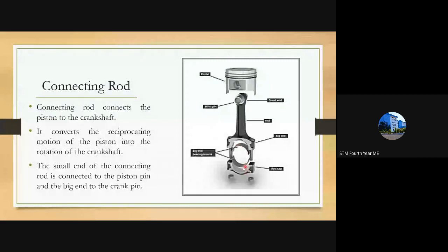Providing these bearings means the thing that will be worn out first will be the bearings. Only after that will the connecting rod be affected. So once for servicing of the engine, mainly the bearings are replaced. The bearings have sufficient working time or a sufficient life. After that, they will be worn out from this position. So before that, we have to change them so that it will not affect the big end or the small end of the connecting rod or any part.